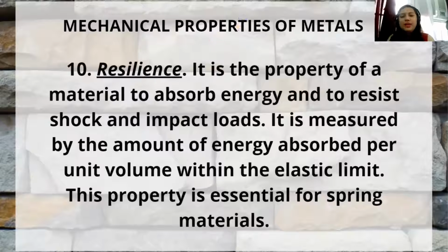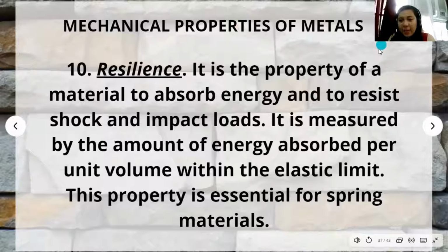There is also one more, which is very important: the resilience. It is the property of a material to absorb energy and to resist shock and impact loads. It is measured by the amount of energy absorbed per unit volume within the elastic limit. This property is essential for spring materials.